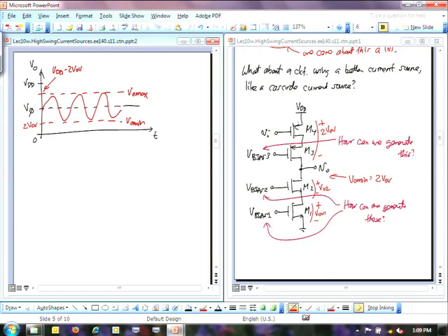So say we needed to get this kind of gain. We had no choice, but we need this gain. We're trying to get a very small signal. We have to gain that up as much as we can. So how can we design these V-bias generators to ensure that we have this maximum swing for this circuit? Okay, so let's make an attempt here. Let's try the simplest thing that we can do, and that's use an MOS cascode current source.